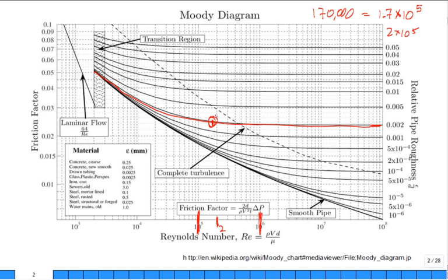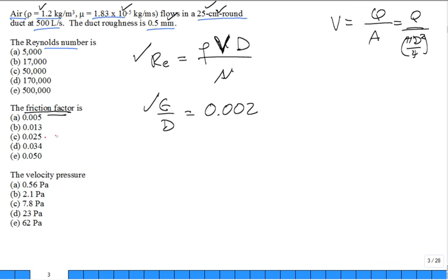What's the friction factor close to? You tell me. What's the friction factor? It's between 0.02 and 0.03. You give me the next digit. 0.02 something. 5. Anybody else? 5. So we run over here and we find that's the closest number. 0.025. You have to do a few of these by yourself to really absorb the material.